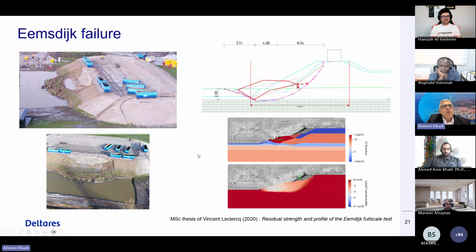And by that also, we do a lot of research, and part of that research is full-scale experiments. So there are full-scale experiments on dike structures under loading conditions and monitoring actually the failure. So the failure is also relevant in this case. We do experiments in the lab, and we do also numerical experiments with tools like MPM in this case to look at failure patterns. And we see more and more that when we are in that domain of failure, that we can really capture the right mechanisms with a tool like MPM.